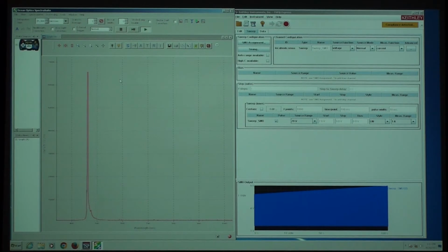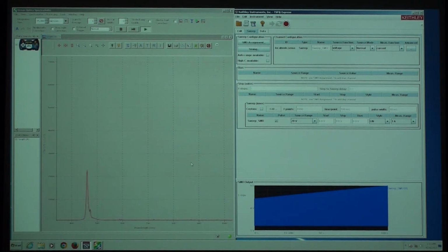So I think there are two things. One is for good electrical contact, but also a lot of waveguides. You need to confine the optical mode. The blue wavelength has a certain wavelength inside the material, and the light has to be guided and made incident on the two mirrors. The refractive index of these materials also changes when you make heterostructures. So using the refractive index, you can make waveguides, and he has taken that into account in this design when he grows the material for waveguiding. So that's the photon design, and we talked till now only about the electronic design.